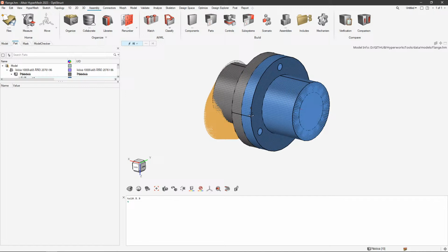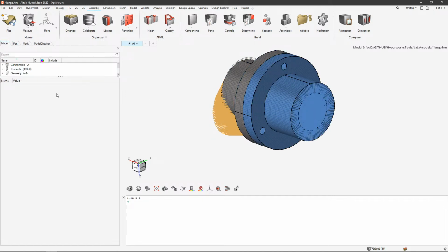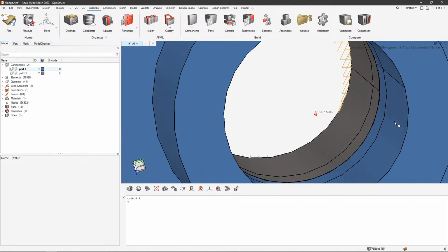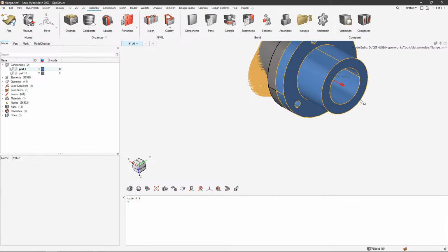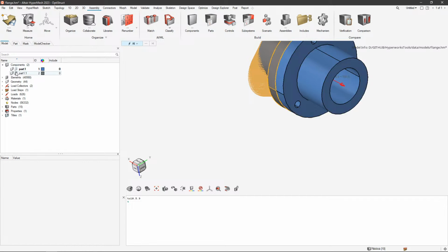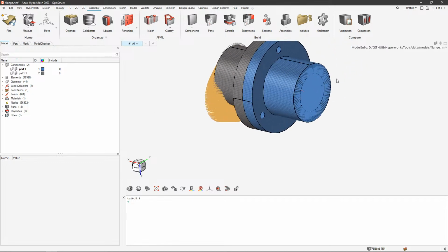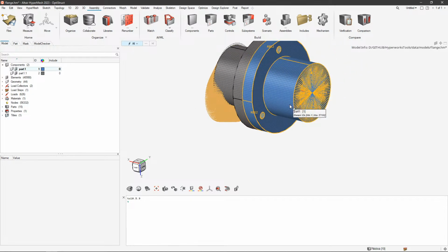And that also reflects the use case here, because if you just look at the model, the load case is just a straight pulling of the force. Yeah, it will be transferred over to all the nodes on this surface, but it's a straight line, straight force, straight vector. Nothing complicated. But if you have something like bending cases, with contact and whatnot, then it will get a little bit more difficult.